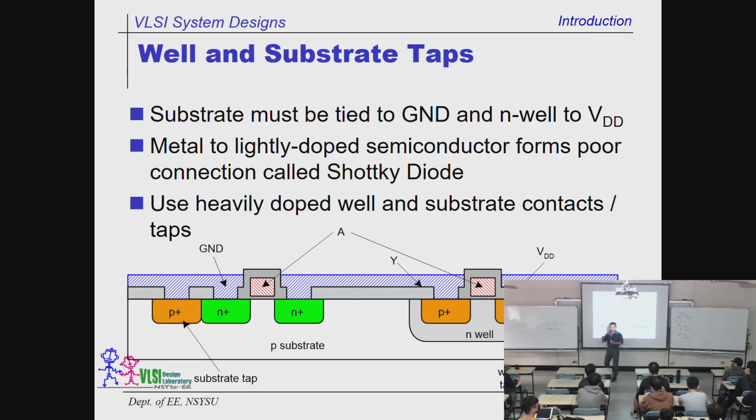So the well tap does not appear in that schematic. However, it is required in the real physical implementation, because the purpose and the function of this one is to clean up all the drifted or random carriers in the substrate.